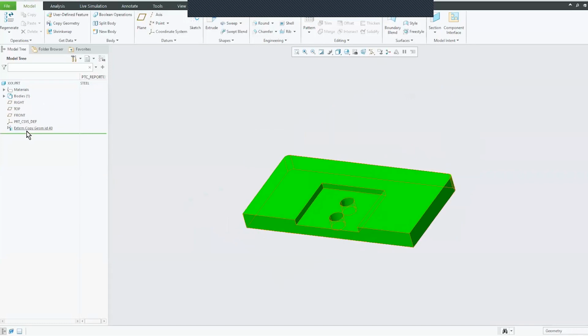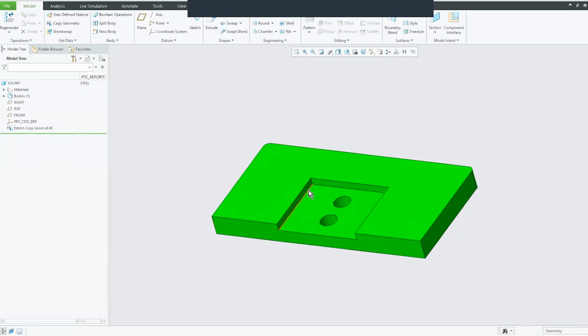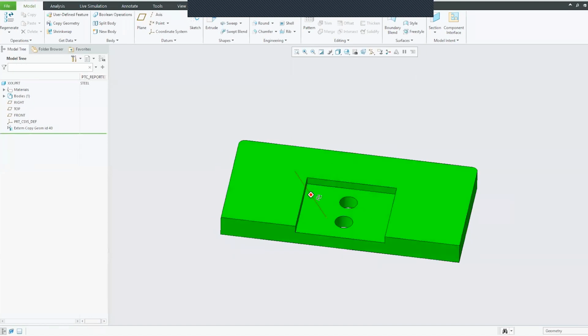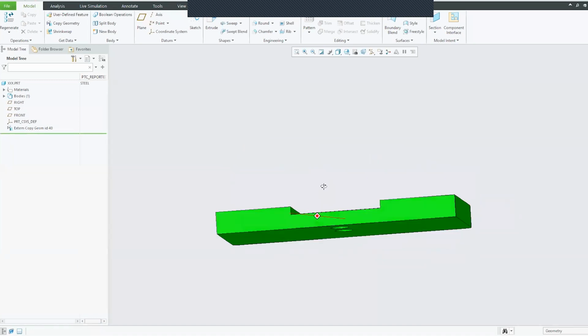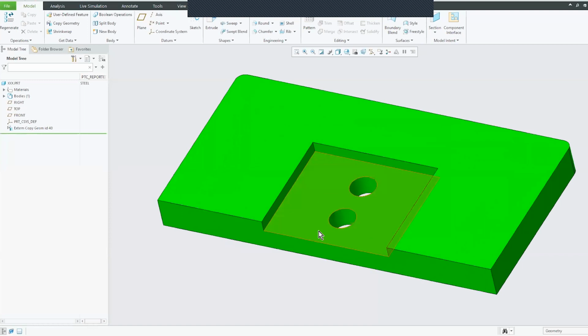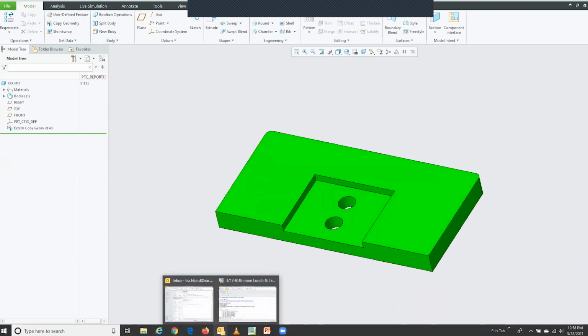It uses copy geom to do that. The downside of this is there's no dimensions. It will follow the original assembly, but if I say show dims in this guy, it's not going to happen. When I saw this, I wrote the product line manager and said, at least use an inherited feature where it copies all the features into it. But they didn't do that. So I'm waiting to see what's going to become of that, because we can show the dimensions when it's in a part, but as soon as we extract it, it uses this as a copy geom, and then there are no dimensions. Sorry, didn't mean to drift, but I wanted to highlight that.